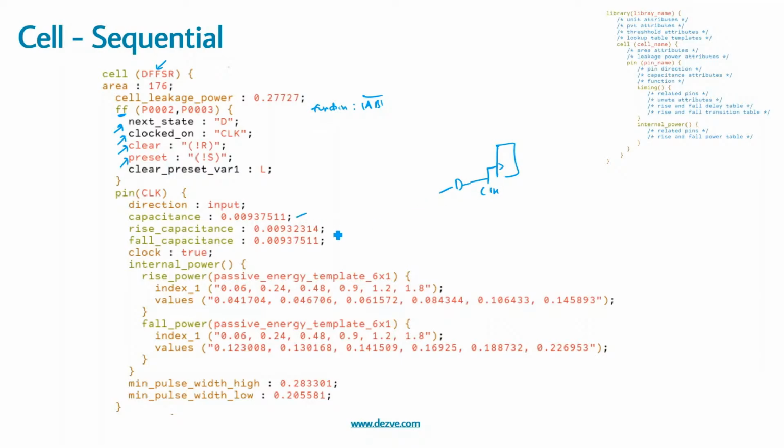So this is the capacitance, the nominal capacitance as well as rise and fall capacitance, if somebody wants to compute this separately. When I say rise and fall capacitance, again it matters. Suppose I have an inverter, and this particular node can change from 1 to 0 or 0 to 1. Depending on that, it might have to charge a different set of capacitance. That might not be very significantly different, but it can be, correct.